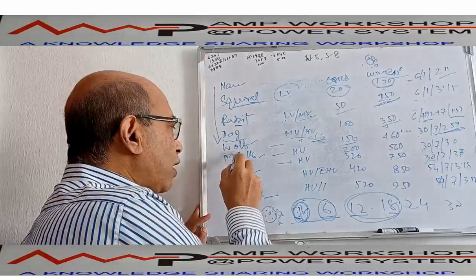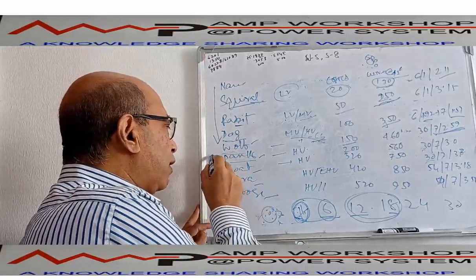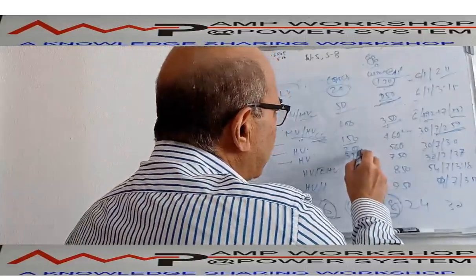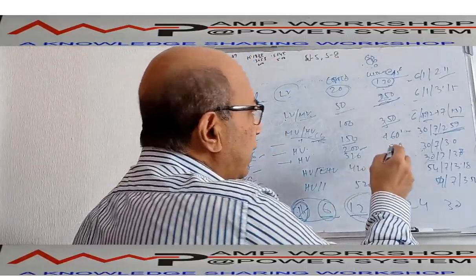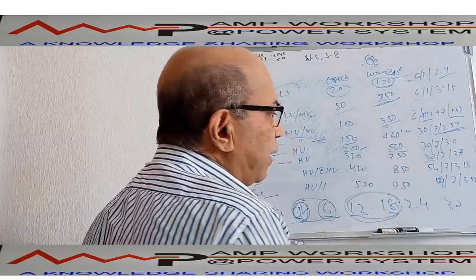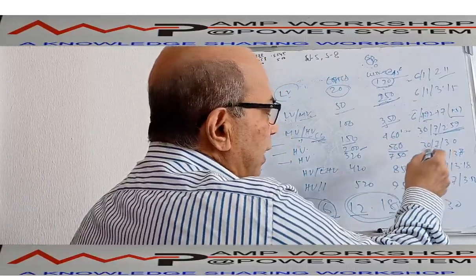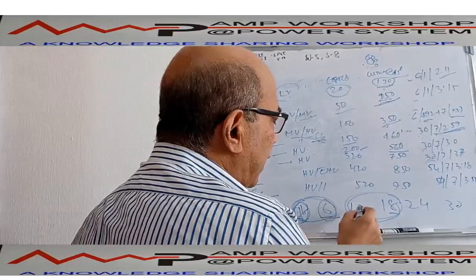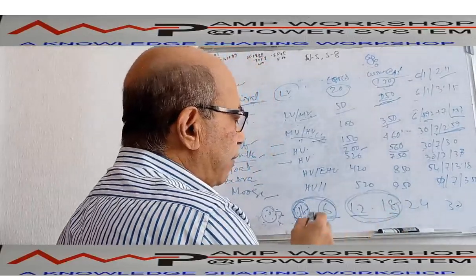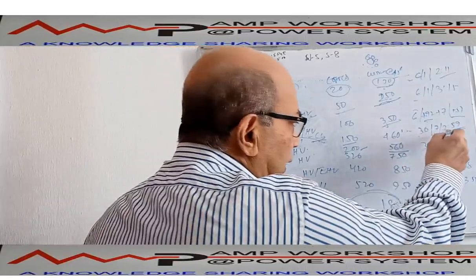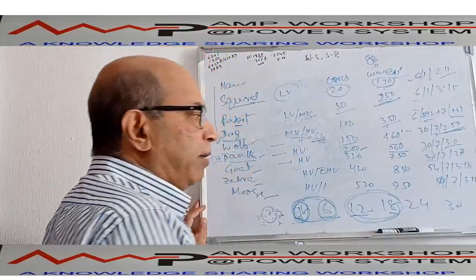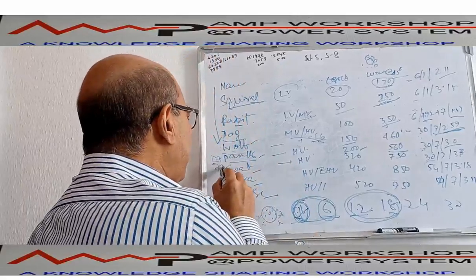Then after the dog there is the panther, which is mainly used for the 132 kV line. That panther cross section is 200 square millimeter. It can carry current up to 560 ampere, and it has the same thing: a center 1 plus 6. These 2 layers are for reinforcement purpose, and 12 or 18 for the conducting purpose. Total there are 4 layers, and all conductors are 3 millimeter diameter, and it can carry about 75 MVA power.